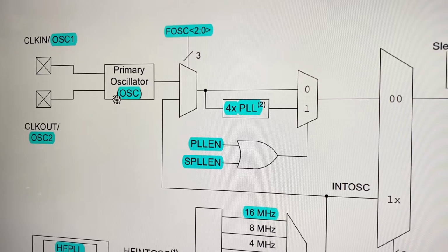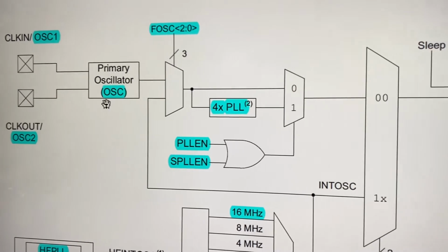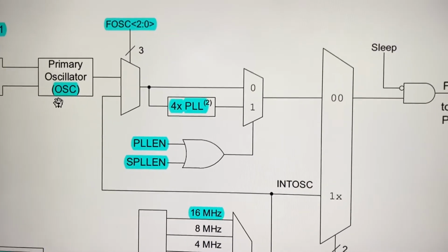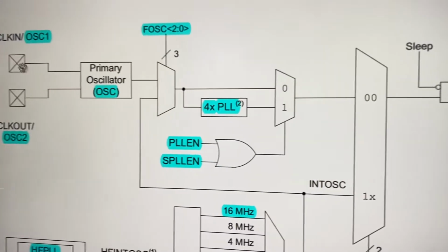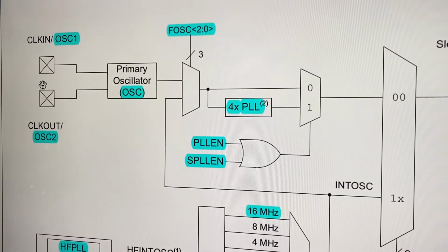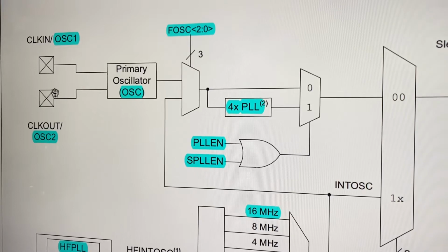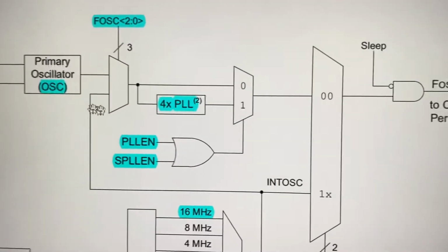So that way, most assembly instructions will require 1 microsecond, and a few of those instructions require 2 clock cycles, 2 microseconds. So working at 4 megahertz, if you want to increase the speed, you can put it here at a 16 megahertz or 20 megahertz oscillator.